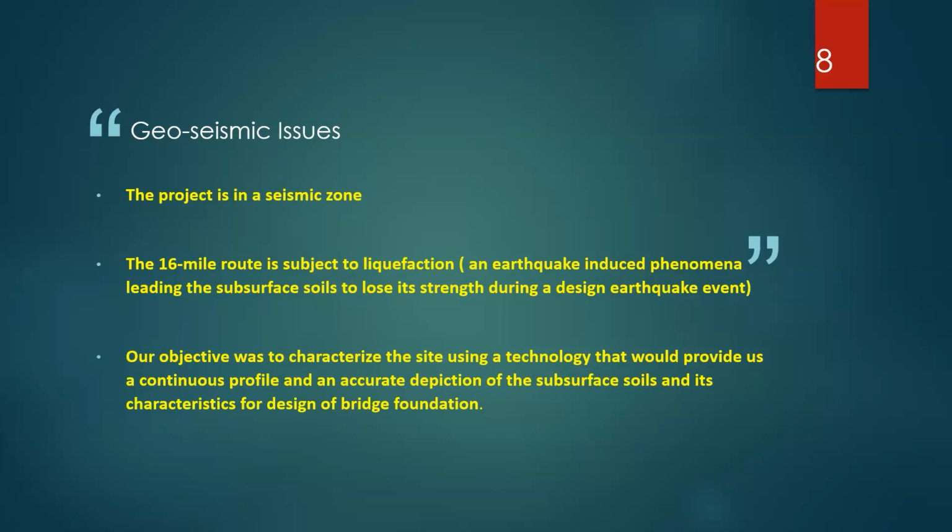And why is this important? Because in the context of geoseismic, you want to capture those liquefiable soils, and if you don't capture them, obviously you're introducing risk and lack of a good performance for your bridge foundations in the long term. So that's an obvious point of using CPT, which we did in this project.